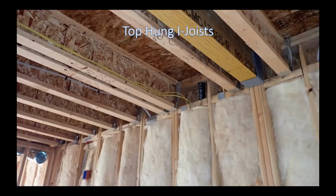And they use a lot of top hung hangers over there to suspend all the joists and beams. As you can see from here, a big LVL beam there to carry a heavier wall load from above. So these are very commonly seen to form all the floor structures.